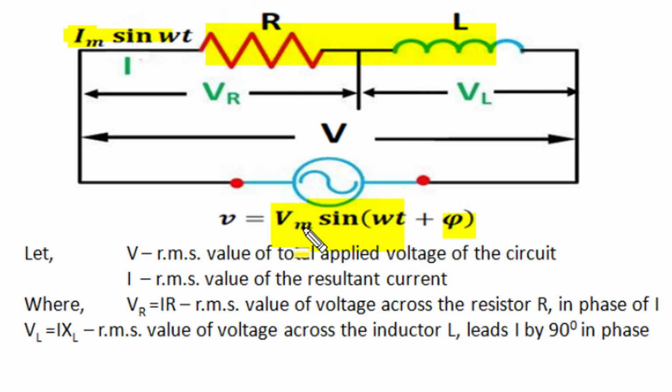And if Vm is divided by root 2, that becomes the RMS voltage across this RL combination. Similarly, RMS voltage across resistance is VR and RMS voltage across inductor is VL. Then we can relate VR, VL, V and current of the circuit as rotating vectors of the same frequency and in the same direction, and when that rotation is frozen at any instant, say at the instant when the current phasor is at horizontal reference, the rotating phasors become simply vectors, and simple vector analysis will fetch a convenient relation between RMS voltage, RMS current and the phase difference angle between voltage and current.